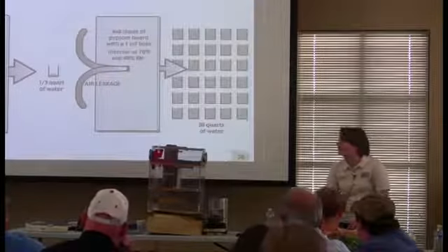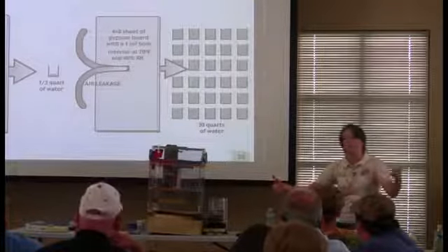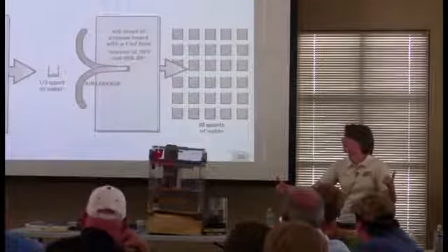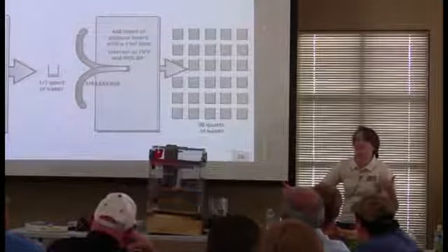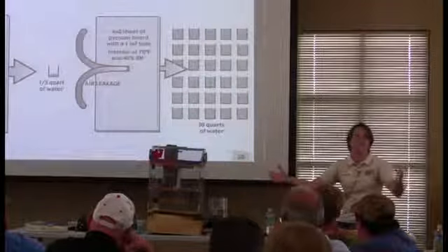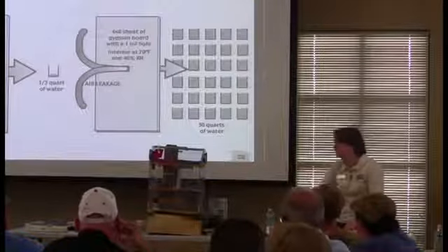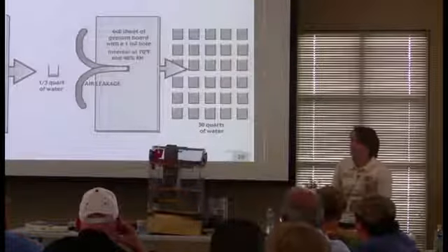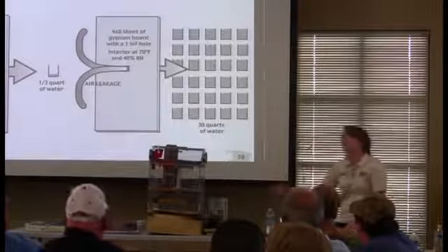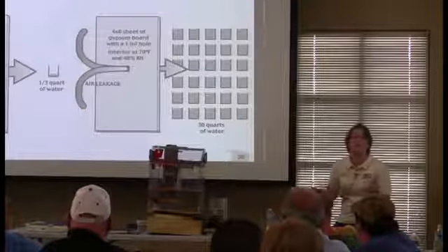So let's recap. Is it more important to put a vapor barrier in a house or to air seal? Is it just a little bit more important to air seal, or is it 100 times, really significant? Yeah, we're talking 30 quarts of water, guys, versus 1/3 of 1 quart. That's just giving you some perspective. Vapor barriers are good, but that's not the main cause. The main cause of water getting into your home is through all the leaks, and through the humidity carried in the air through those leaks.